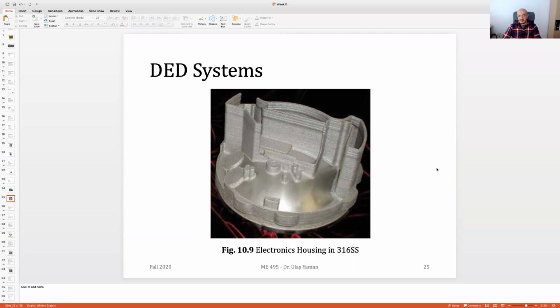It's quite difficult. In material jetting, we don't have very powerful metal systems. In material jetting, we prefer to have polymers. We can try to do testing, as your friend pointed out, but it's not easy. You need to have many molds. With a single mold, you obviously cannot do it. You need to have multiple parts in your mold, and it will be quite costly.